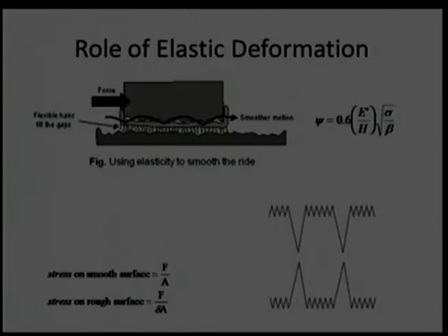There is a possibility of 6 times stress, or another possibility is that if there is a high stress equivalent to the elastic limit, naturally the asperities will bend and will allow other asperities to come into the picture. In other words, if the load is more, more asperities will come into contact, reducing the stress back to the elastic limit stress. That is preferable, and the maximum in that case is if the whole real area is equivalent to the apparent area, then we can say the component can tolerate that much maximum force.